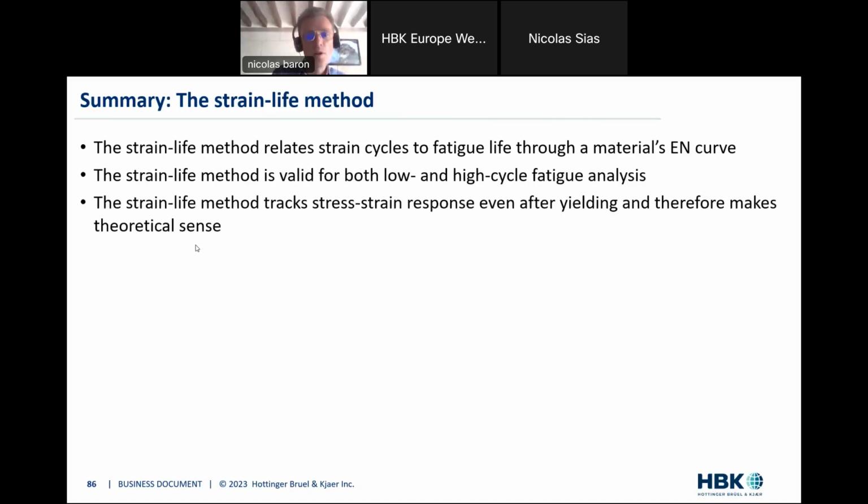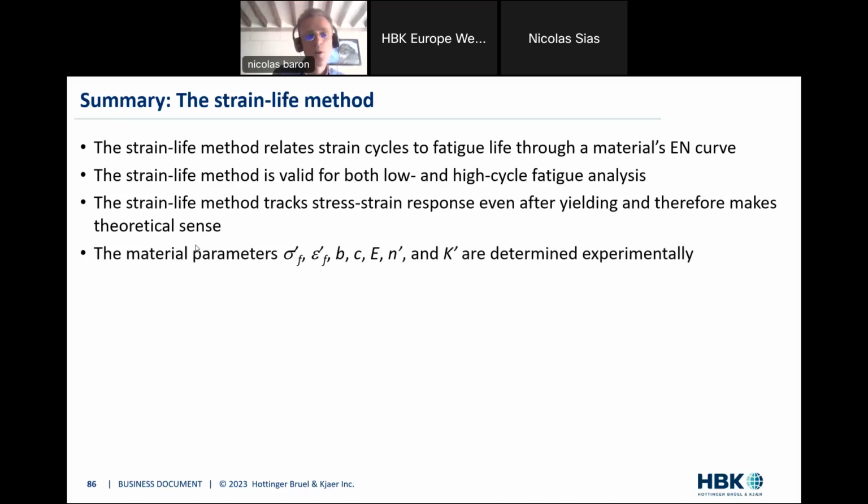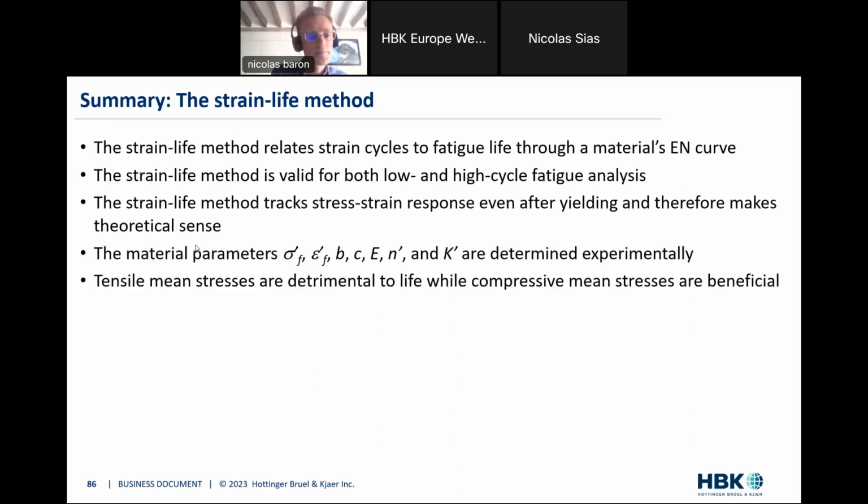It always works. And the nice thing is that it takes into account plasticity, and it's very fair to use it even after yielding, which was not the case with the stress life. So it's much more general than the stress life. It's more involved in terms of material parameters. You need to have such curves graphically characterized. That's why you need to have this data set of material available, probably produced by expert people. Otherwise, you don't have access to these curves.